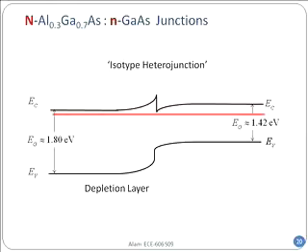Now, one thing you realize on this band diagram is that although both sides are N-type, on one side you have a depletion region, right? Because charges have been pushed back on one side, so you have a depletion charge. However, on the other side, you have accumulation. On this little notch, you will have electrons.